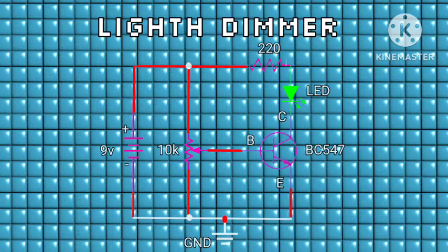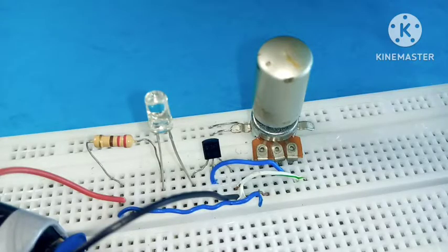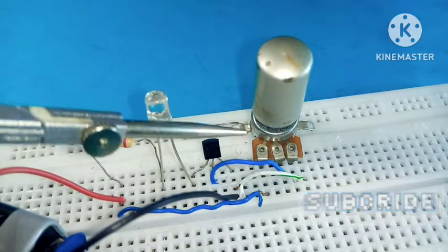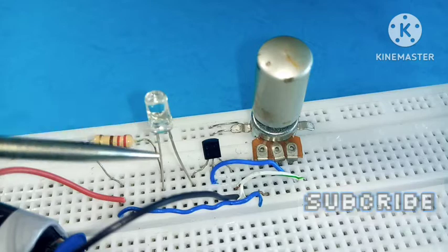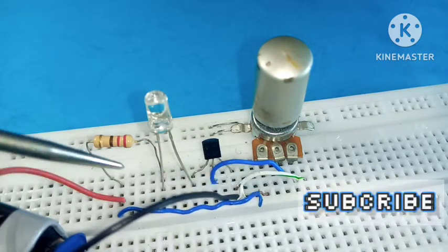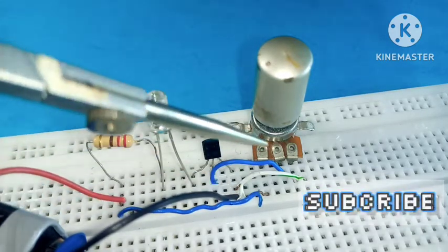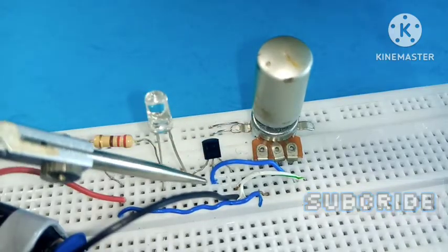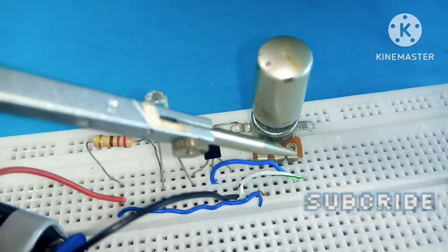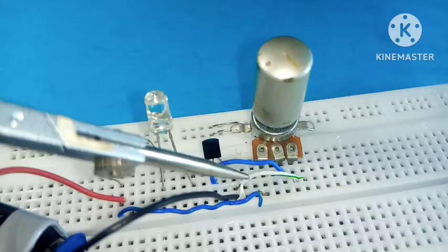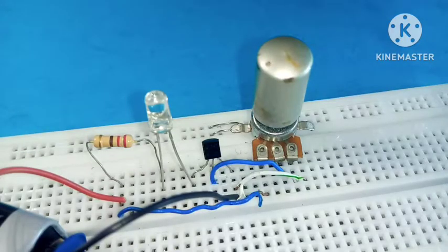Here on this circuit we can find a potentiometer which acts as a voltage divider that can be varied. According to our schematic we have everything in place, and here is the potentiometer. We can see the first lead connected to the power supply rail, the middle lead connected to the base pin of the transistor, and then the last lead connected to the emitter of the transistor.